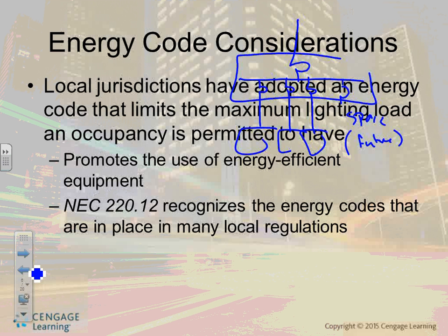In the main panel, they size the main panel, and a lot of them even put a circuit breaker there. So they know they need another panel for the addition, maybe two panels, depending on the size. Let's just say two. I have two for future. So these will be, let's say, 225 amp panel each. Both of them, you just put the circuit breakers and say spares future. That's how they do them. So no pipe, nothing, they're just sitting right there.